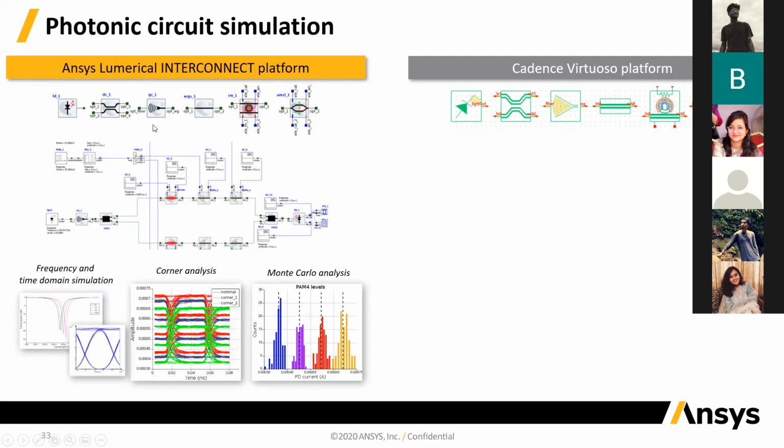The grating will behave slightly differently for every single fabrication that you do, and the ring will behave slightly differently from one fabrication to another. So when you run your simulation, you want to account for these variations and make sure that if you fabricate this circuit 100 times or 1,000 times, it'll still perform according to your requirements every time. This is where statistical simulation comes in.